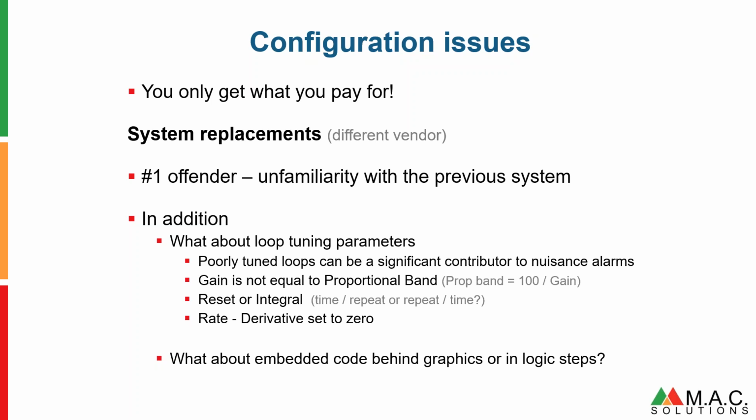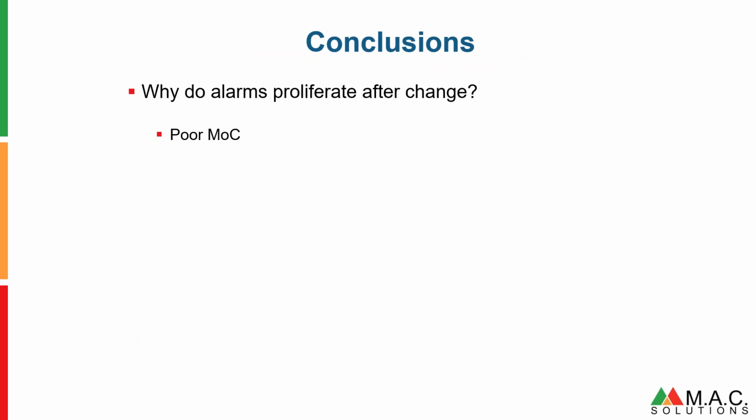So they had no interlocks to prevent the nitrogen valve from purging the reactor, and so it just kept pressurizing and pressurizing until the bursting disk ruptured. That wasn't taken as part of the migration. They didn't understand the old system, so they just did what they knew, and that caused problems. So, understanding what you're doing and making sure you document everything and you keep an eye on people.